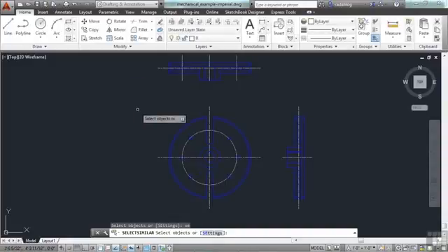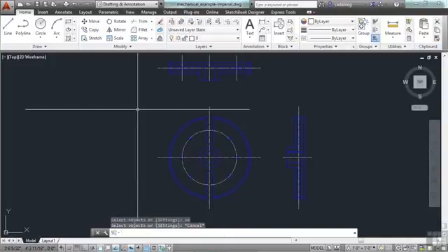And there you go. AutoCAD gives you several different ways to select objects. Remember some of those whenever you go to start. You have your crossing window and your selection window. You'll use those most often. Plus, you can pick an object one at a time. You have the fence command. You have the select similar. You also have your window polygon, the WP, or the crossing window polygon, which is CP. And you have your shift key, which you can use to unselect things. This will save you a lot of time and effort through your drawing process.